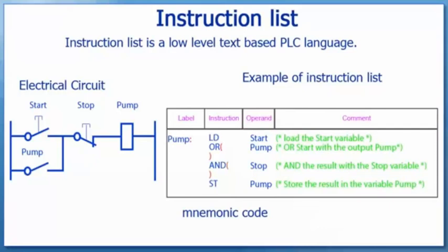In this example, the value of the start is loaded and is ORed with the value of the pump, which is the latch. The result is ANDed with the stop input. The result is stored in the variable pump.